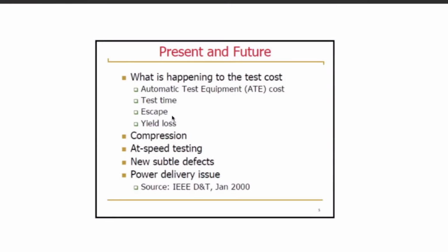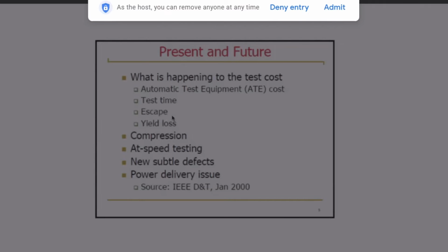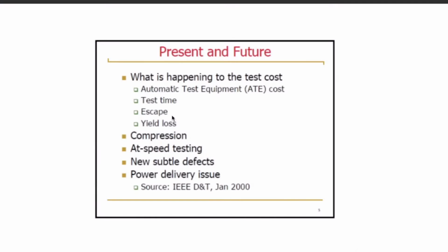Now we can see how we are applying the patterns, input patterns, to test the circuitry. So basically ATE has limited memory space and limited bandwidth to send the patterns to the IC we have embedded on this ATE machine. So we use test data compression here.